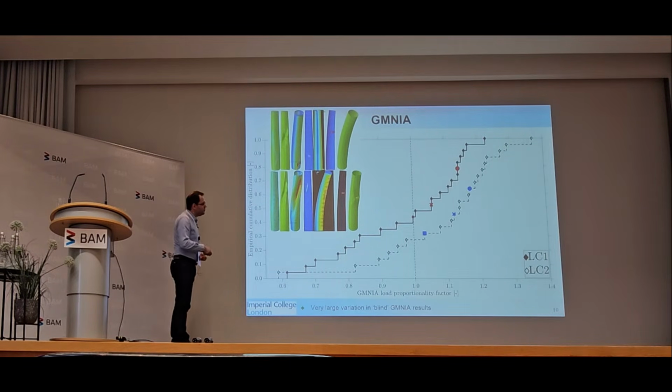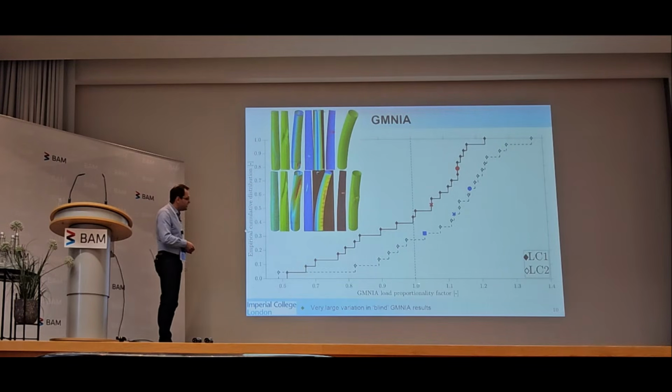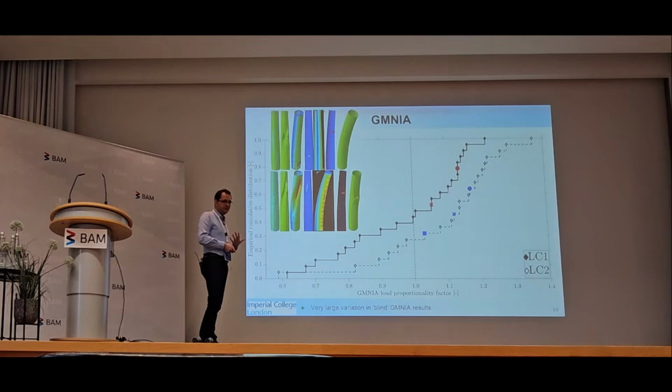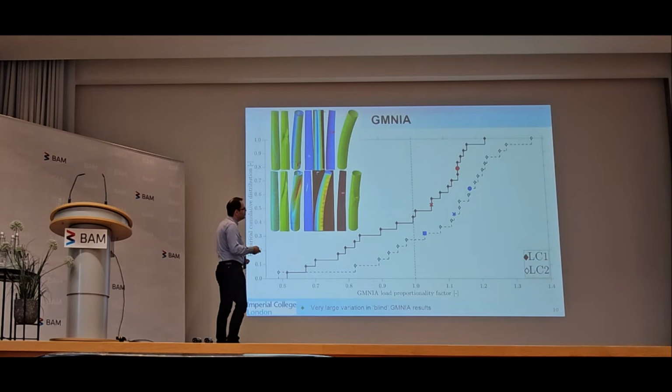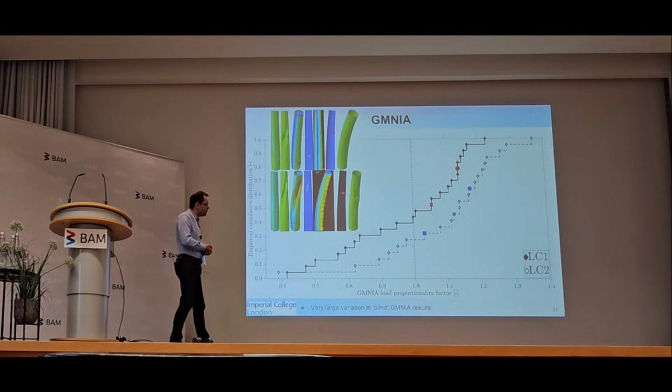I mean, the community could not decide whether this tower is safe or not, clearly. Any GMNIA less than 1 means that you cannot achieve your full set of design modes that you're applying. Anything greater than 1 means you can, with some reserve.